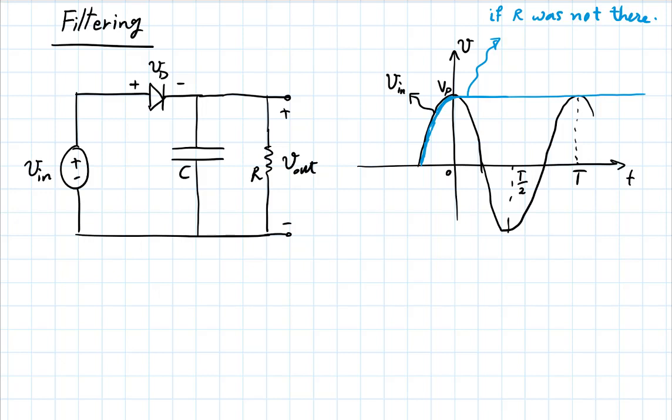It will start losing its charge to the resistor by setting up a current in the resistor. So there's that path. And so this is what happens. You initially have that rise, but then the capacitor will not retain its charge. It will start discharging. Maybe let me exaggerate this a bit. This is an RC discharge.